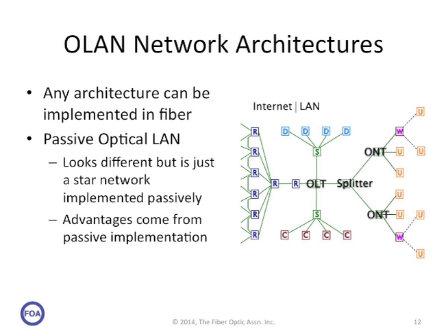Optical LANs, based on fiber to the home passive optical network technology, work very similar to a star switched network, except for the fact that one of the switches is replaced by an optical splitter. The optical splitter works as a splitter going downstream to the users and a combiner going upstream to the optical line terminal, the central switch in the system.